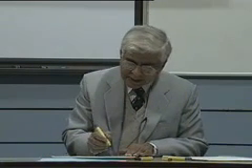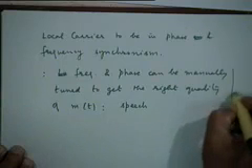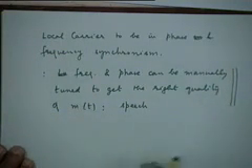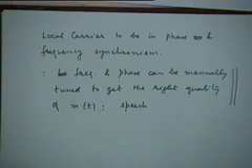So that's something that is known by experience, as also it can be shown by analysis. So see if you can work out what is the sensitivity of this demodulation to theta(t), right? If you just attempt to do that and see what kind of conclusions you can reach, you will probably start agreeing with this, right? But if necessary, we'll take it up in our tutorial. But at the moment, I'll just make the statement that this happens to be the case, that it is easy to at least tune it manually for applications like speech transmission, right?